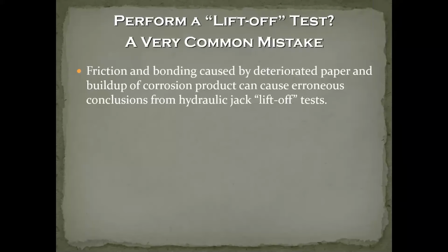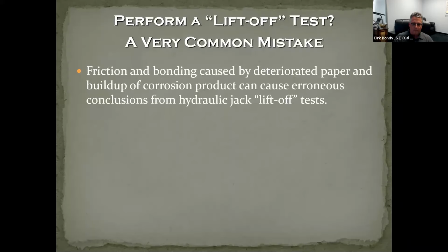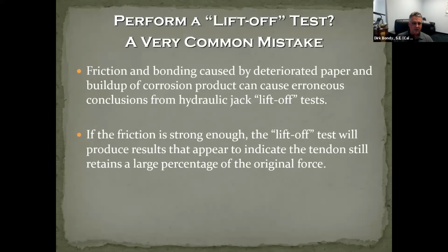If you get those high jacking forces, you may misinterpret that, and many engineers do, as saying, well, there's still plenty of pre-stress in those tendons. And you could actually be checking a tendon that has been broken somewhere. So a lift-off test is probably the worst way to try to determine if you have lost pre-stress.